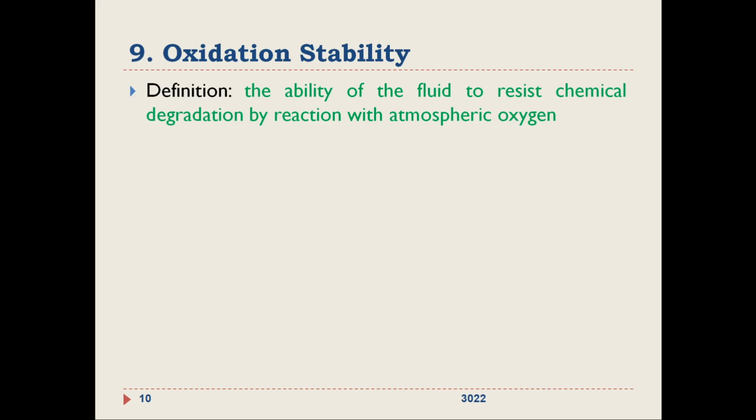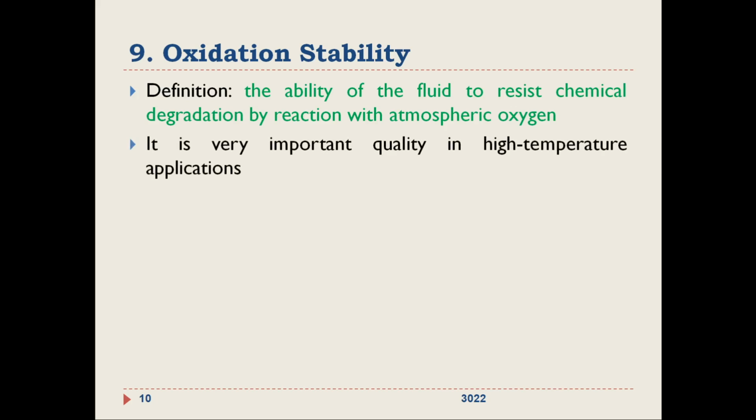Whenever the hydraulic oil is in contact with atmospheric oxygen, it should not react with it and form an oxidation layer. It is very important for high temperature applications. It is a matter of aging, resistance to aging.